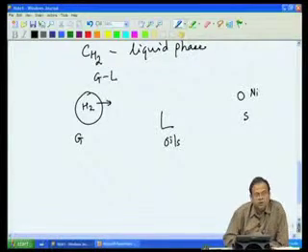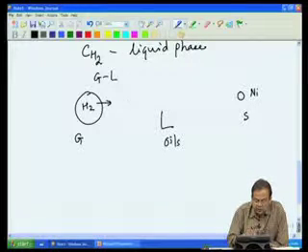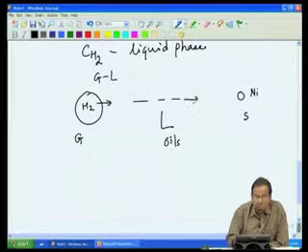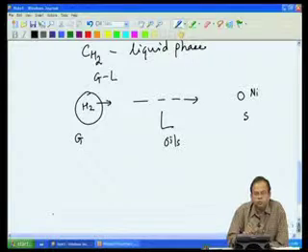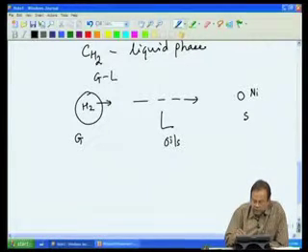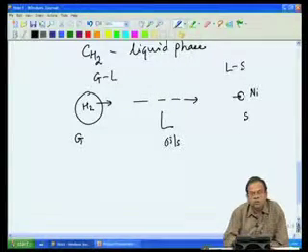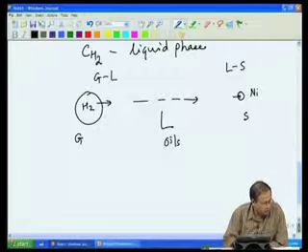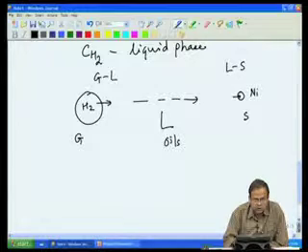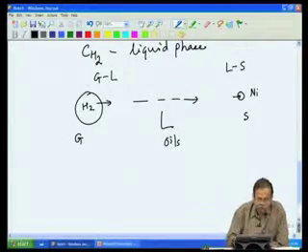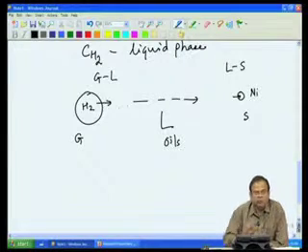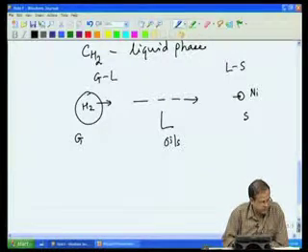So, gas liquid mass transfer, then in the bulk due to the motion of agitation, then to the catalyst, and then further reaction in the presence of the catalyst. Or in other words, we now have a 3-step process, of which important are these two mass transfer processes.